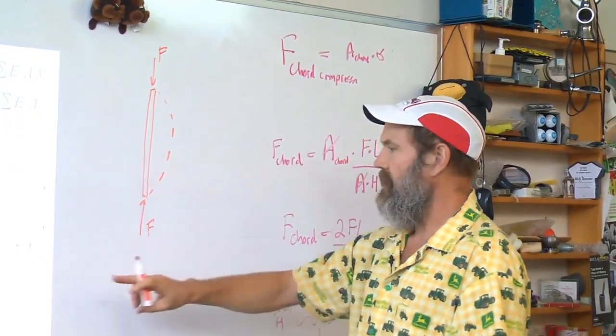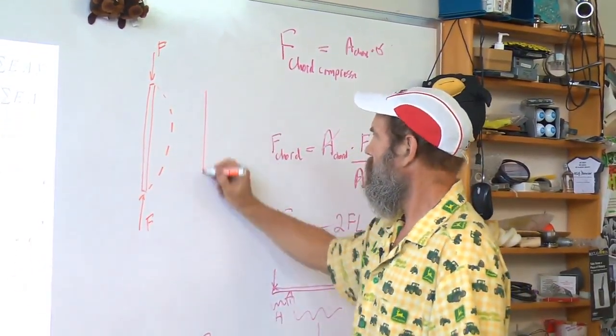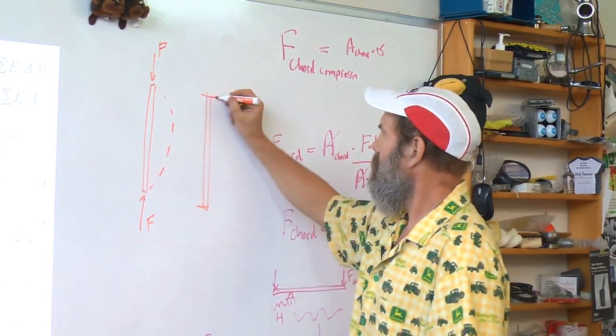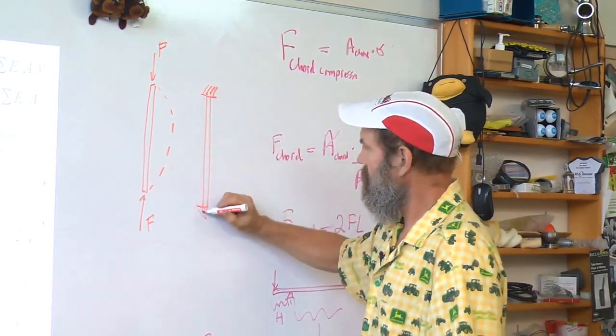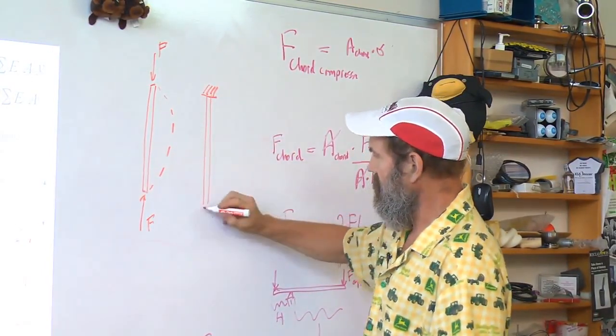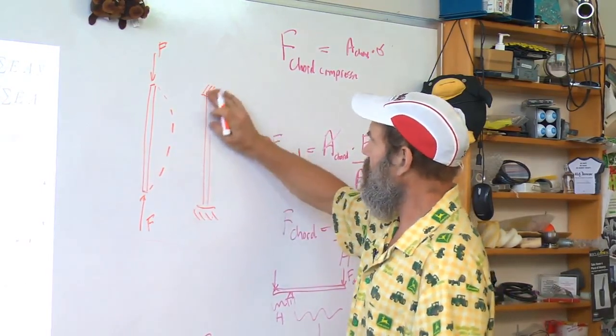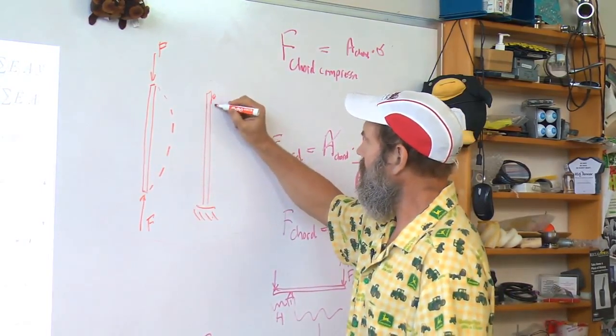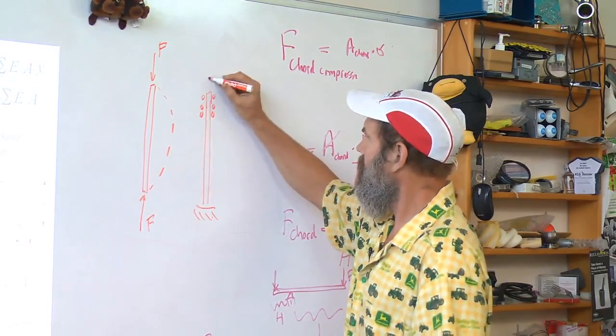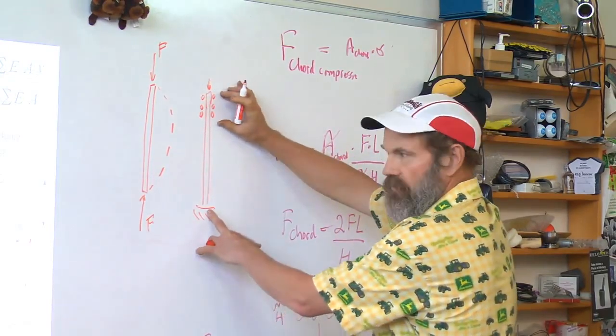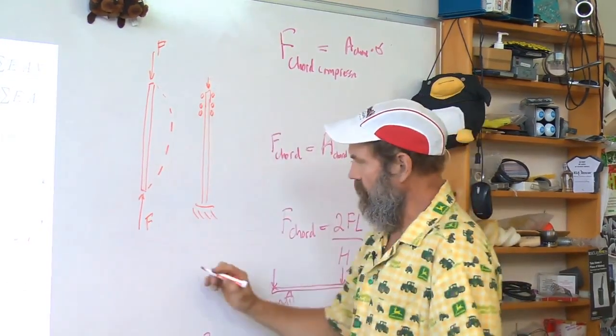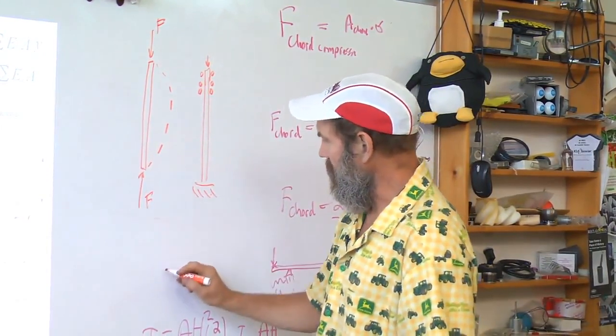And does this column in a truss look like it's built in? In other words, one end would be built in and the other end is guided, so the slope is kept zero at both ends? Or does it look like it's simply supported?